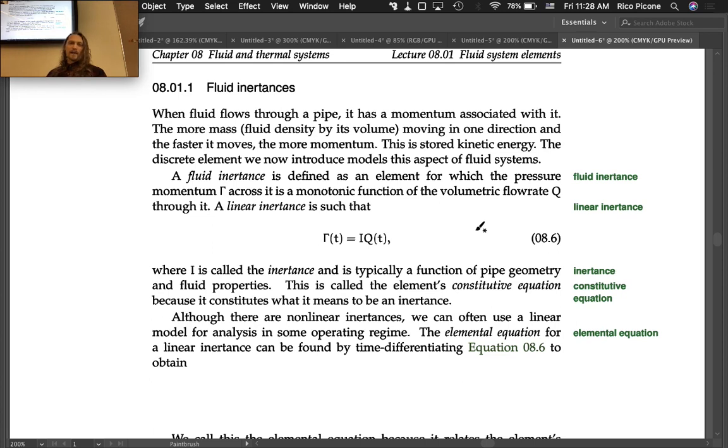So, isn't that like the fluid hammer or the water hammer, where you shut it off and then you can hear the noise of that? Yeah, so a water hammer, or a fluid hammer, is there to try to dissipate that pressure wave. You'll see them stick out near the end of the pipe, and if you slam the valve shut, it helps to dissipate some of that pressure wave that builds up.